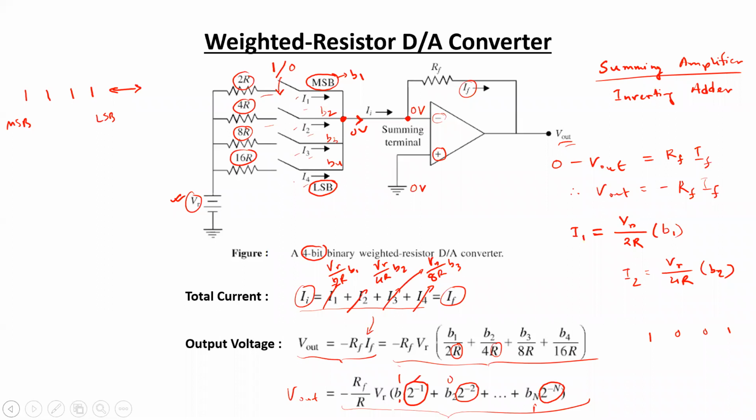Yes, you can do that. You can either connect an inverter circuit along with the reference voltage, or you can also connect it at the output side. So using an op amp you can do that. If you set both the values of the resistances at the input side and the feedback side to be equal, then suppose you are getting a negative output voltage over here, that would be inverted and you will get the positive magnitude.